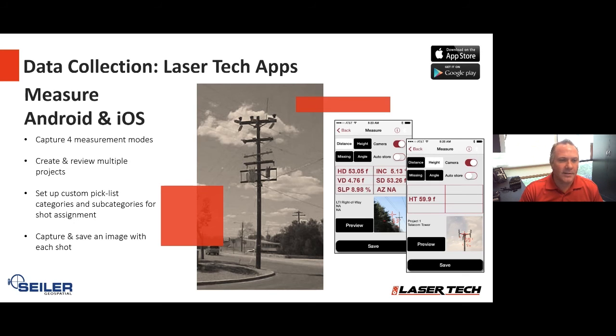that we interface with. One is we design our own apps to work with our laser rangefinders. This one here is called LaserSoft Measure. It's a free app that interfaces with the lasers that have communication. And you see here on the right-hand side, it captures the raw data values, the horizontal distances and everything. So right there, you're able to see the values being captured, or if you're doing a height measurement, you can see that value populate, or a missing line value. And you can make some generic notes, get some documentation.